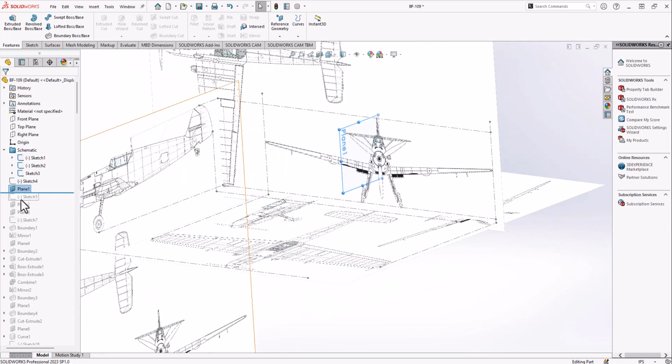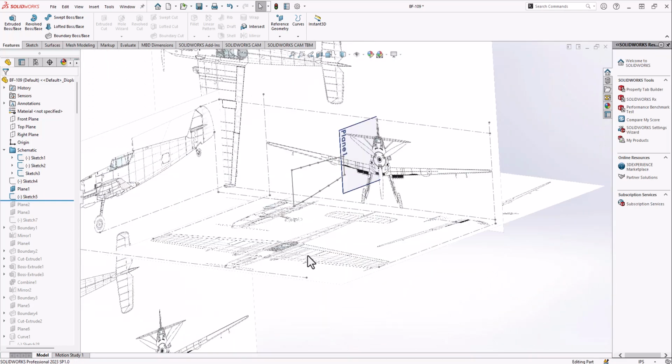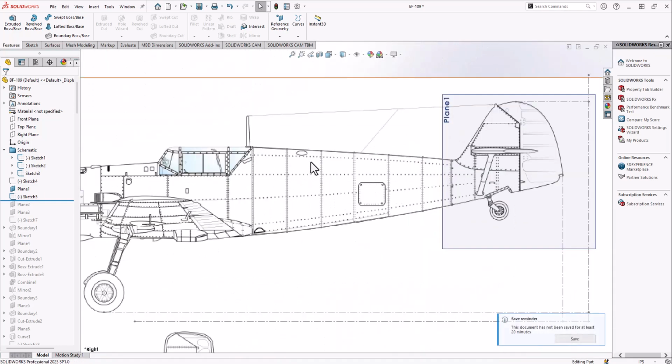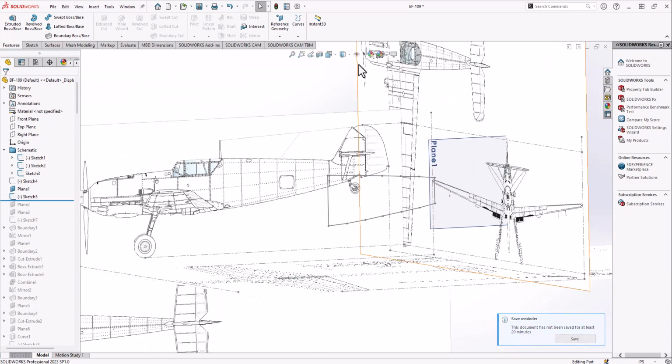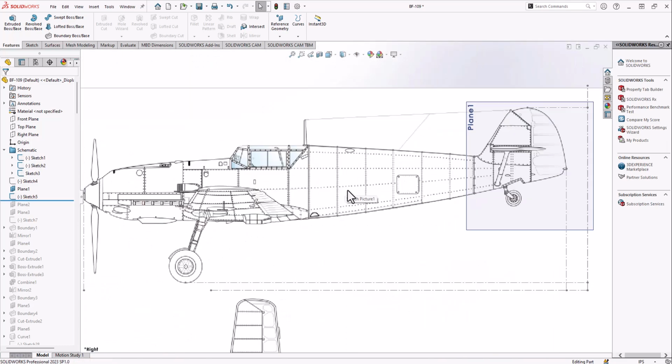So the first steps I take in this case are I just draw out an outline of what the aircraft looks like. So I'm starting with the tail section. I just trace it out with some discretization at each of these seams. And I'm just using this midplane, and I'm tracing the right-hand view to get some guide curves. And then I add two more planes.